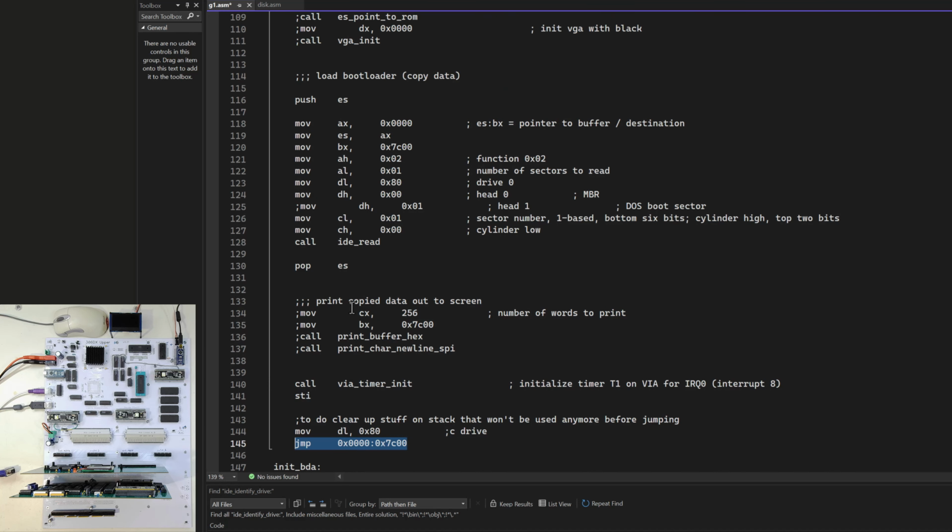So when the system turns on, I quickly read some information about the drive. I get that populated into some spots in memory. I might output it in my debug window. But then I turn around and say, okay, now copy. I've got really this master boot type of record, and I want to basically copy it over. So I've got a master boot record, and there's also this DOS boot sector, two different locations on the CF card, but I get this pointed to the MBR, I get that copied over into RAM, and then I turn around and I jump to that.